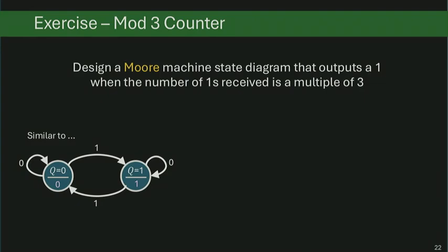With 2 states, you can actually prove that it's not possible. That's because, think about how much information content you need to differentiate. You really need to differentiate between 3 different modular levels. So 2 states is definitely not enough information content to accommodate that many conditions. Right? 0 mod 3, 1 mod 3, 2 mod 3, they have to be differentiated. So they have to be remembered somehow. You cannot remember 3 different scenarios using 1 bit, like with 2 states. So you do need a few more states.